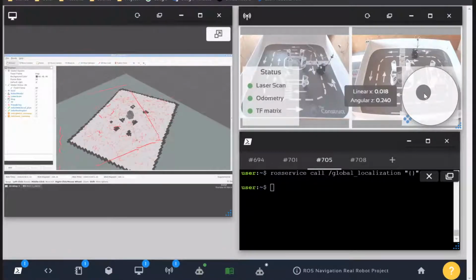For example, I made the robot rotate a full circle. As the robot gets its laser readings, and by the computation of the AMCL, it changes the probability of its location in the cloud points. So some of the points get more probability that the robot is occupying that location. Let's move the robot a little further.